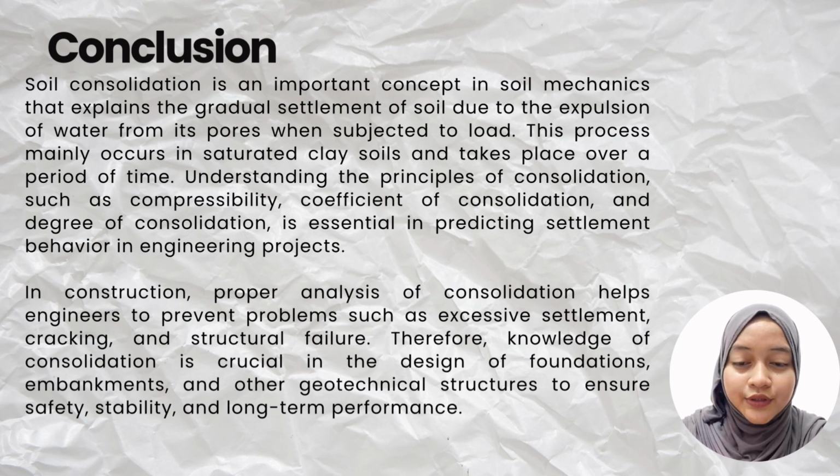In conclusion, soil consolidation is an important concept in soil mechanics that explains the gradual settlement of soil due to the expulsion of water from its pores when subjected to loads. This process mainly occurs in saturated clay soils and takes place over a period of time.